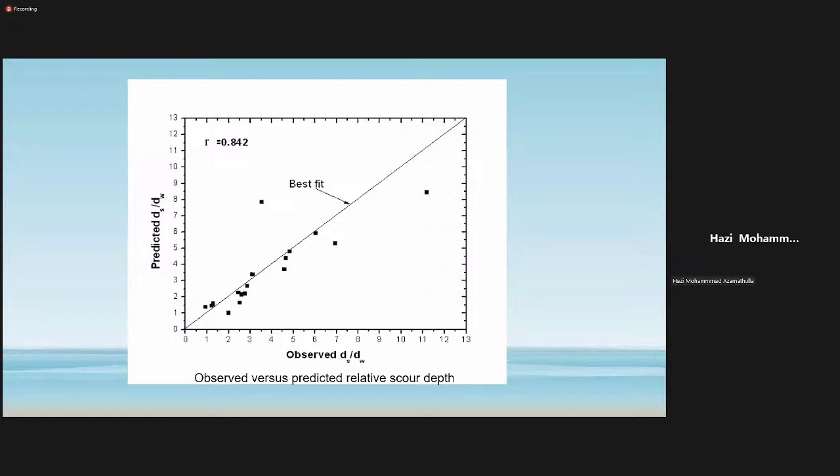You can see, anything only telling with the models, so you must have a scatter plot. You can see two outliers here. One is under prediction. This is the line of best fit, a perfect line, the 45 degrees line. On the x-axis is observed scour depth, then y-axis predicted. Your correlation coefficient is 0.84, so how much will R square come, maybe 0.7 or something, right?